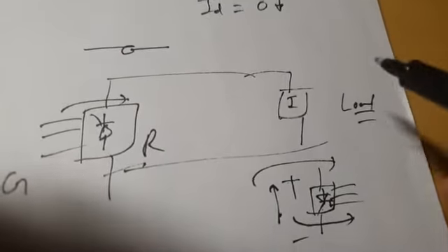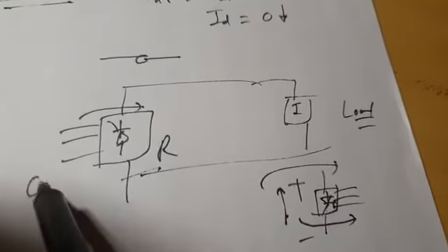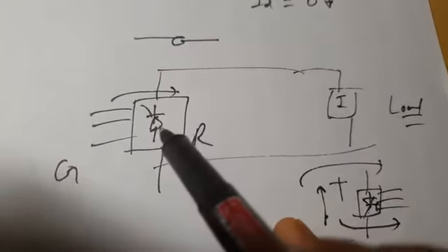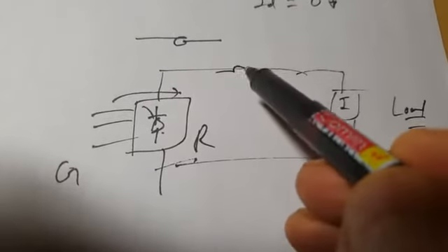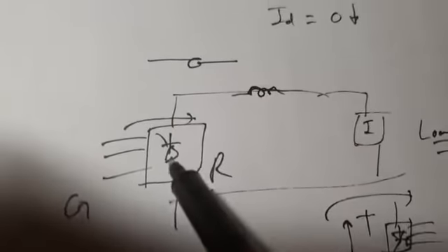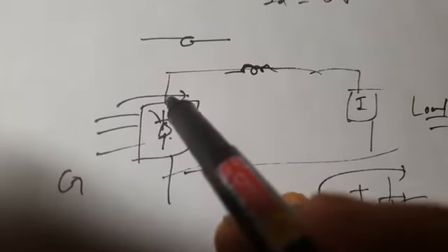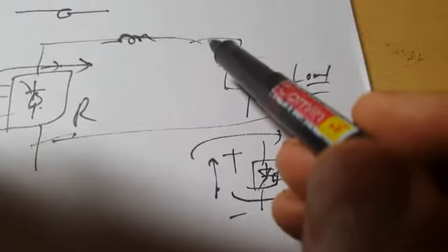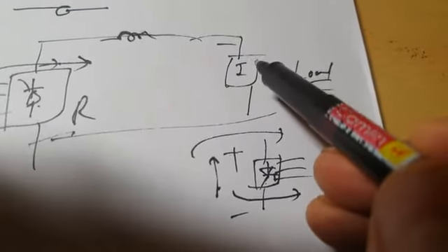If your power system is an isolated power system, which is not the case in modern power systems, then on this side you have a generator and on this side a load. If you want to transmit power from generator to load over an HVDC transmission line, this is your rectifier station, which converts AC into DC, and power flows in this direction. Then you have to have an inverter here which will convert DC back into AC. And what type of inverter?